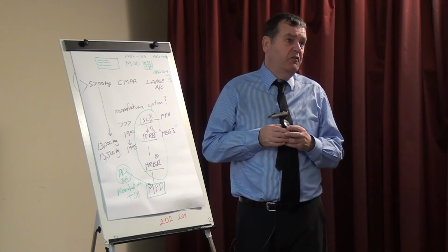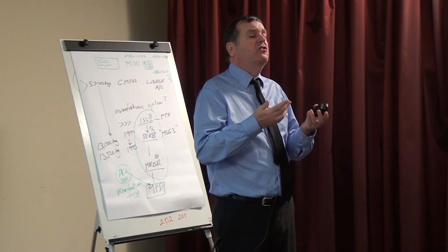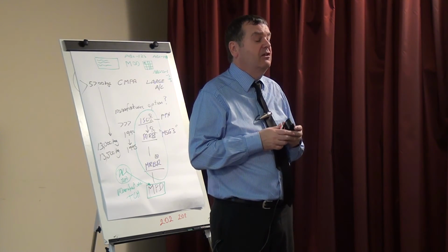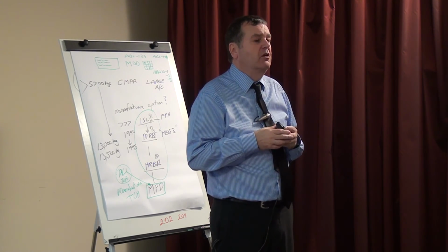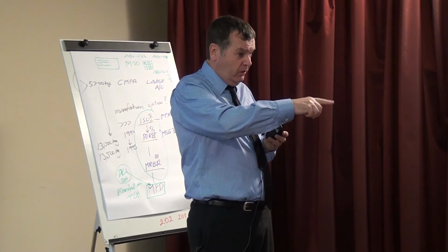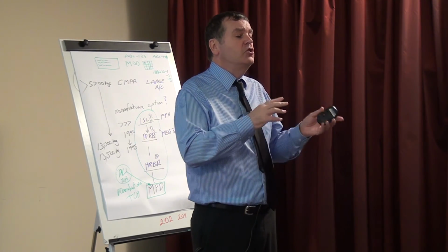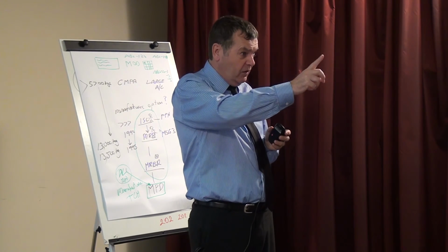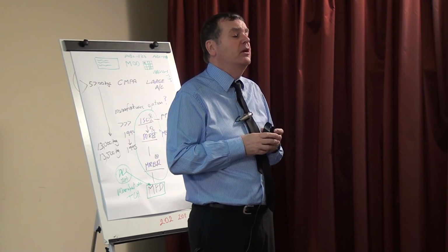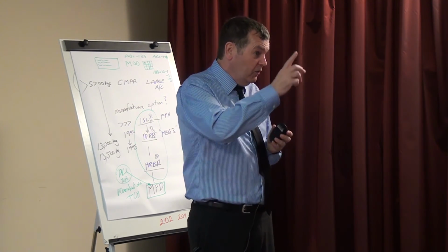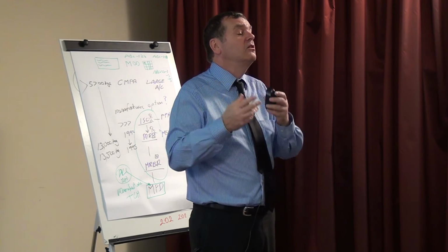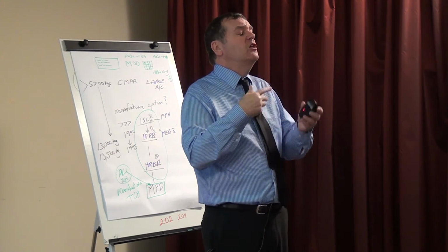So let's start off, if we're talking about hydraulics, let's go into the flight deck. Let's look at what we've got in our hydraulic system. Let's look at how the hydraulic system functions. What can we see in the flight deck? Well, we can switch on the hydraulic pumps. We can see the pressure. So if we just run one hydraulic pump and we can see that the pressure is correct, then we know that that hydraulic pump is doing its job okay. If the pressure is a little bit low, we know maybe that that pump is deteriorating, so we can change it. And this was the philosophy.